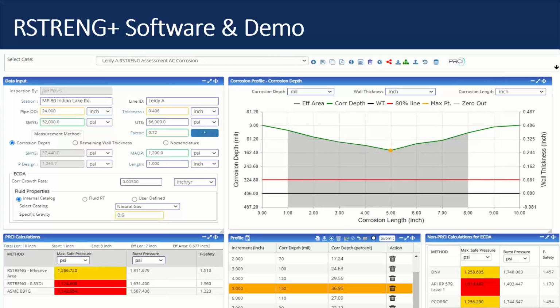You could do it manually, and you could do it very correctly with some of the better manual pit gauges. And then we have optical tools, optical imaging, and they're plus or minus a mil, and so are some of the manual tools, plus or minus a mil or 1/1000th of an inch.